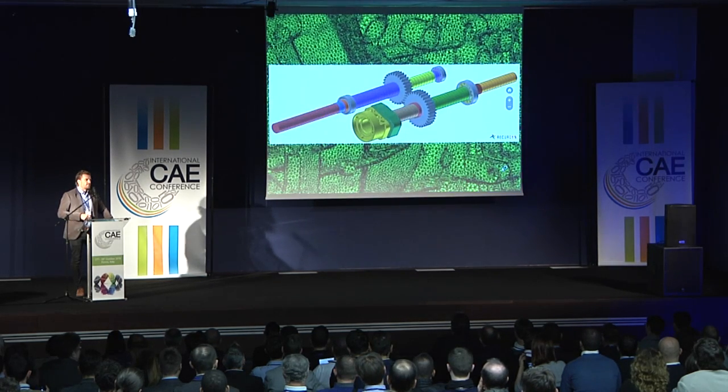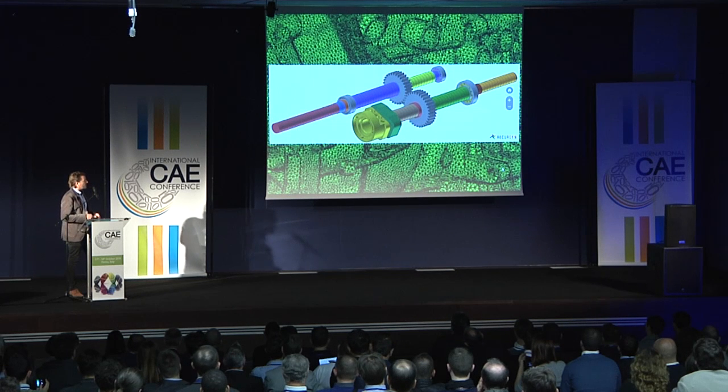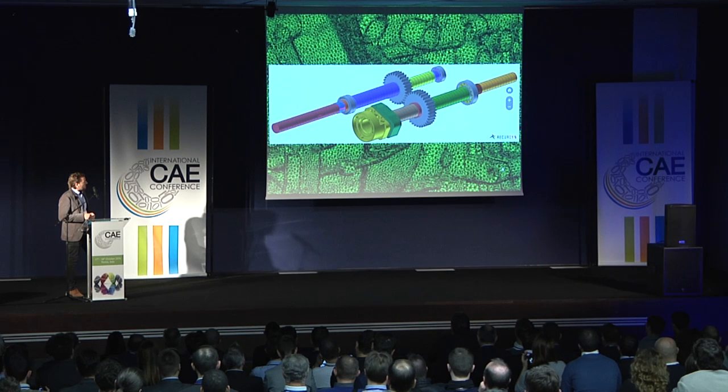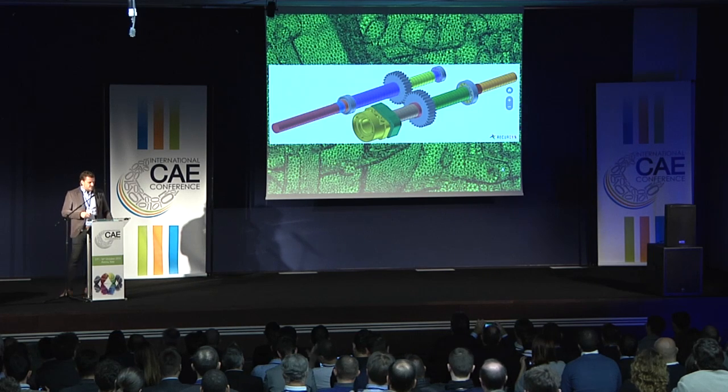And the powertrain, as you see, is a very simple setup. It's got only 2 shafts, 1 gear wheel section, and 4 bearing positions. The shafts are set up with beam elements to keep the bending, and for the contact between the 2 gear wheels, I used a 3D gear wheel contact, which sits right here.